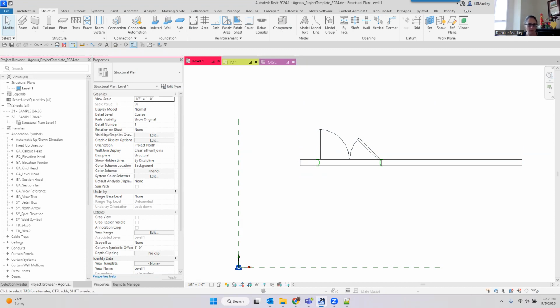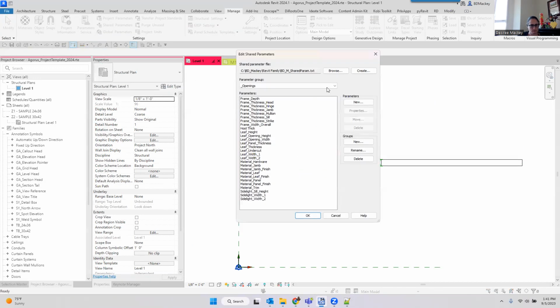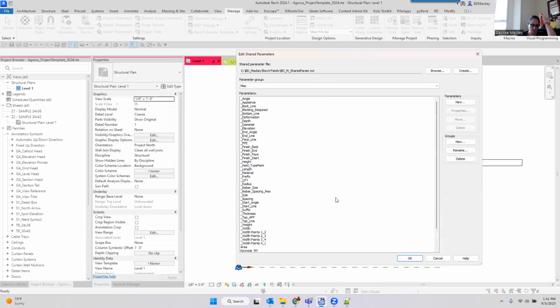You sort of already answered, do you have a method to keep your shared parameter file organized? To a point, most of that. So for me, when I'm talking shared parameters, I do a lot of general shared parameters. And what I mean by that is, first off, I use underscores for all my shared parameters. So I know my shared parameters have underscores in them.